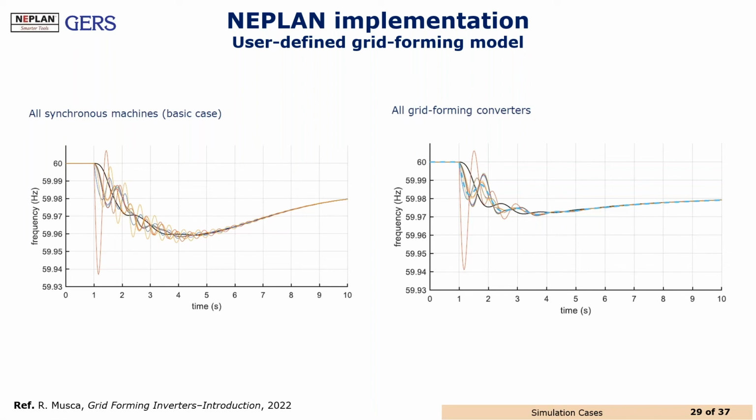For example, if the frequency is too low, for sure we know that the system cannot support that for long time periods. Typically, some countries are able to support the frequency control in a time of 20 seconds. In other countries, 10 seconds are allowed as a maximum control. But again, that would depend on the grid code requirements per country.